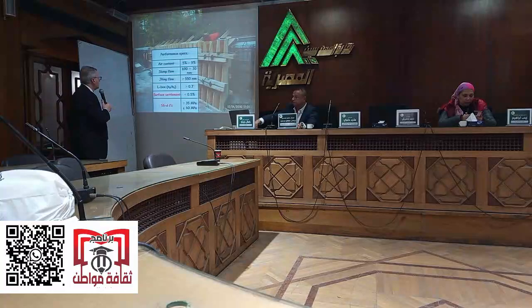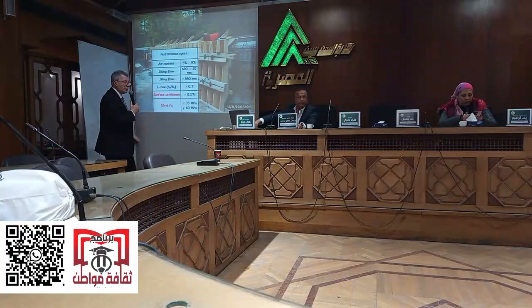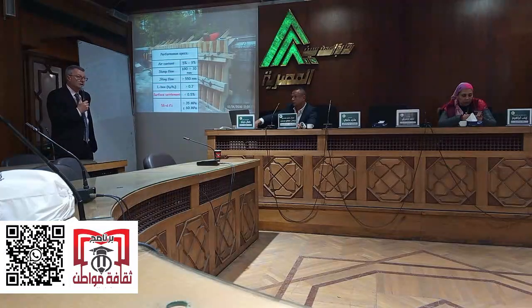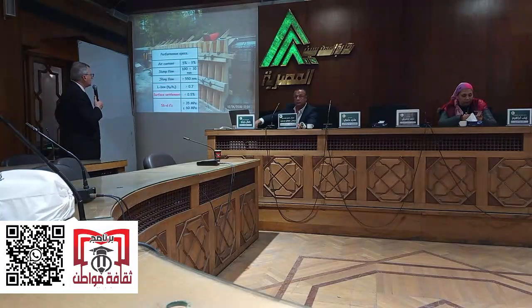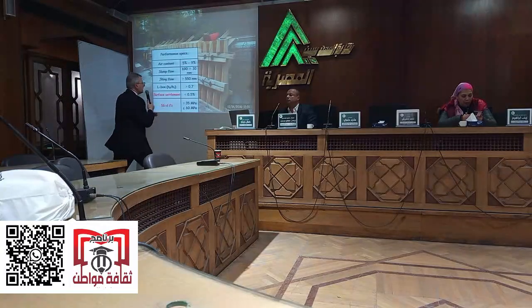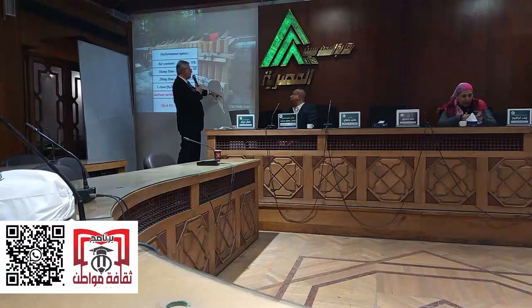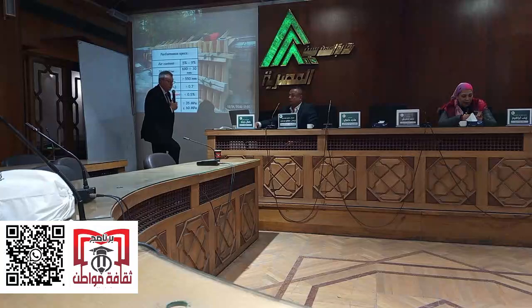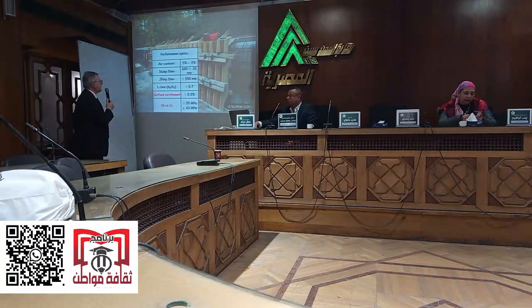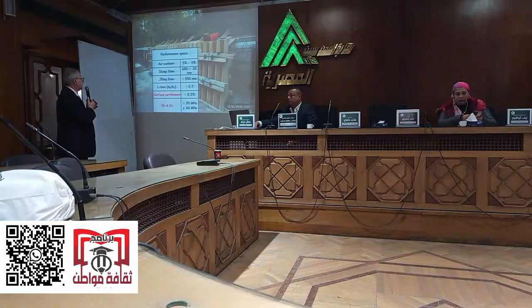Next. So this photo here is from the year 2000. This was one of the first SCC repairs anywhere. It is a retaining wall in downtown Montreal with a lot of corrosion. The architects designed a bell shape, very small at the top and very wide at the bottom, which made it very difficult to put in a vibrator and vibrate the concrete. So they decided to use SCC, and here you have the flow properties.